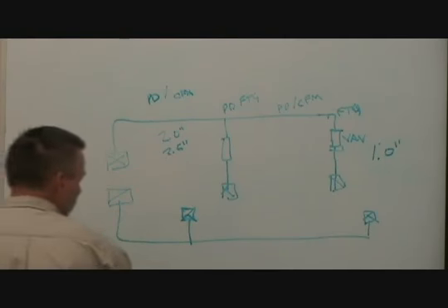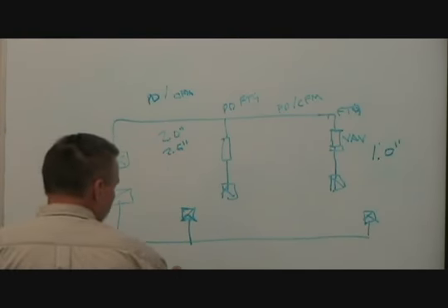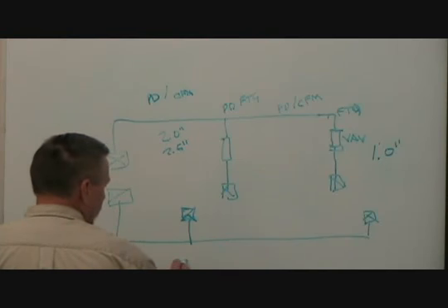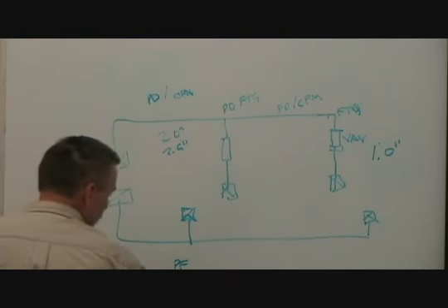And in the air handling unit, you got filters, you got coils, whether it might be 1 or 2 coils. You got pre-filters that have a preheat coil, cooling coil, maybe a diffuser on the fan, and then some plenum losses.